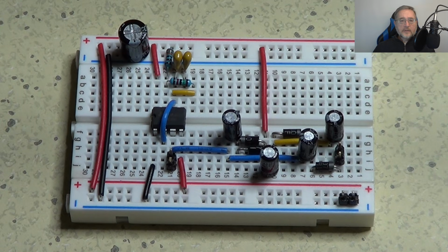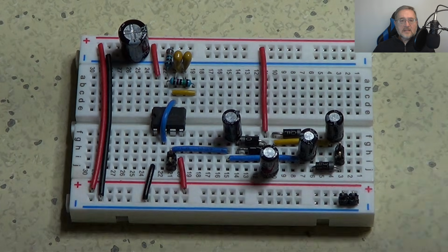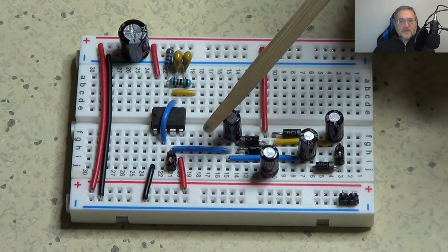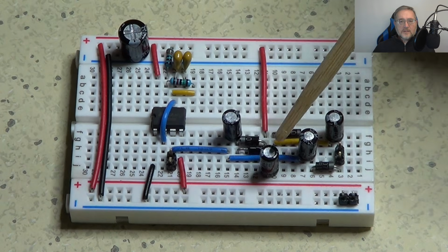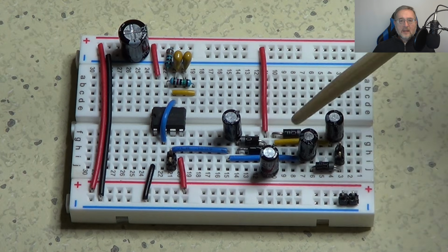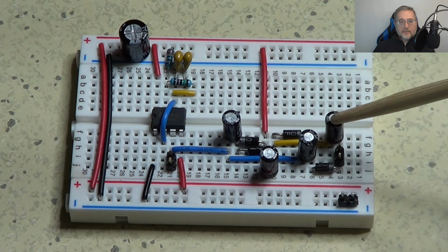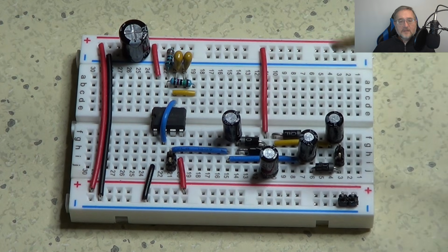Here is the new circuit, which I assembled again on a breadboard. This side is exactly the same as the previous circuit and provides the square wave to make the rest of the circuit function. These capacitors and diodes make up the first stage of this voltage multiplier, and this is the new stage with its 2 capacitors and 2 diodes. And it is exactly the same as the first stage.